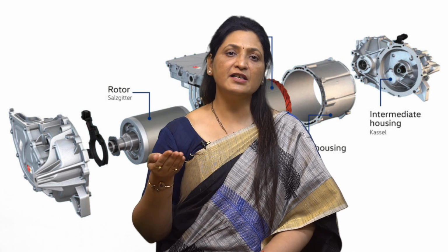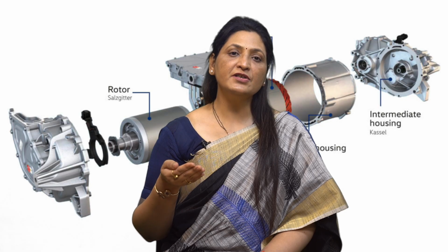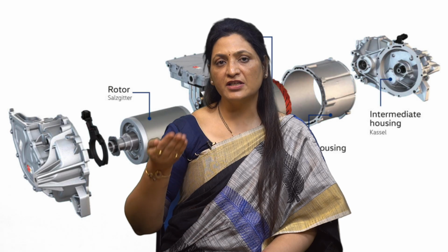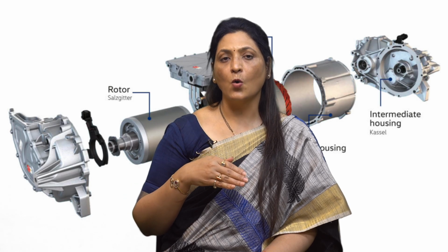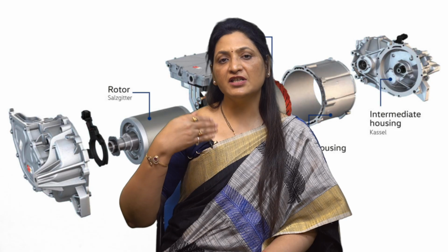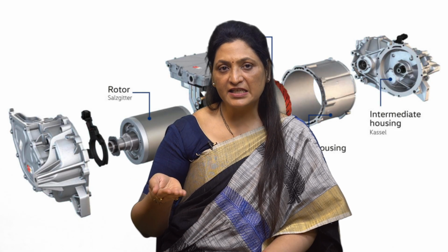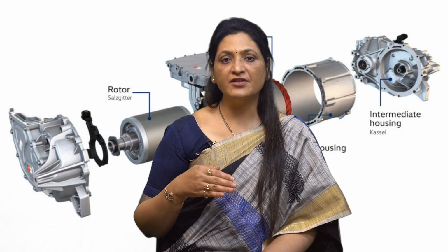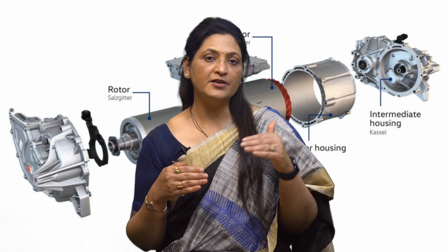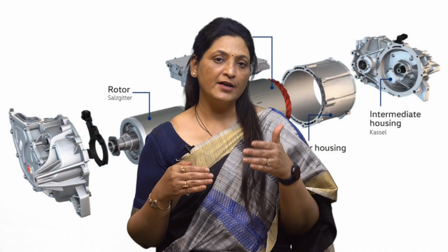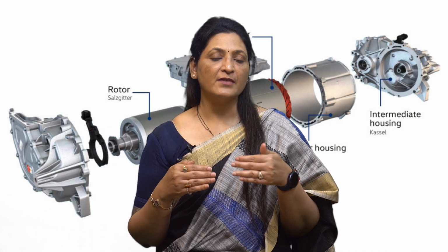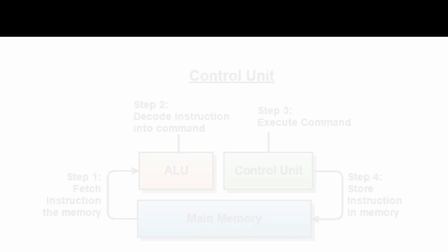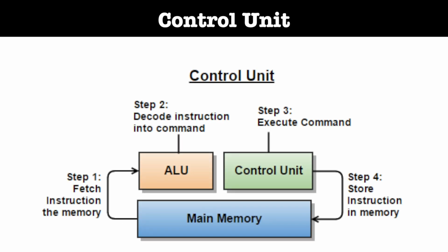The third category is the switching circuits. Switching operation is required to achieve one of the following things: for changing the motor connection to change its quadrant of operation, for changing motor circuit parameters in discrete steps, for automatic starting and braking control, for operating motor and drives according to a predetermined sequence, to provide interlocking, to prevent maloperation, to disconnect the motor under abnormal or faulty conditions. So, the next component of the drive is the control unit.